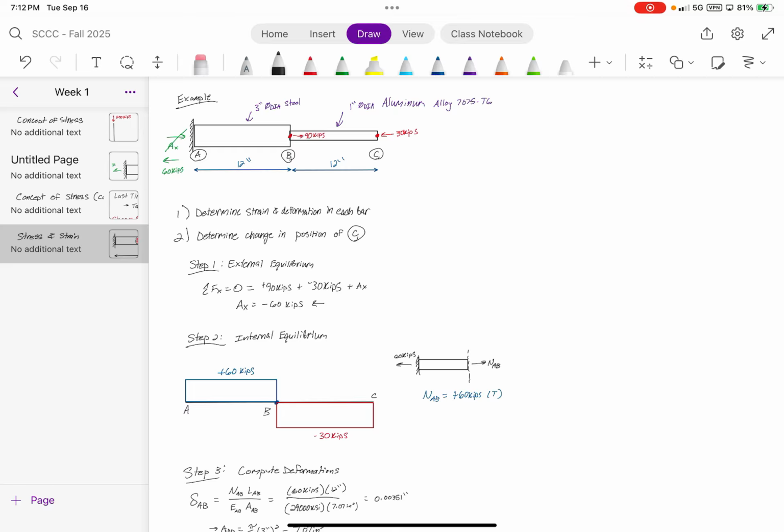So there, you're gonna have 4 bolt holes. So you would take the diameter of those bolt holes, multiply it by 4 times the flange thickness. And then for the web, it would be 2 bolt holes times the diameter times the thickness of the web. And that's the area that basically gets trapped. You add those together. Make sense? Yeah, I got it.